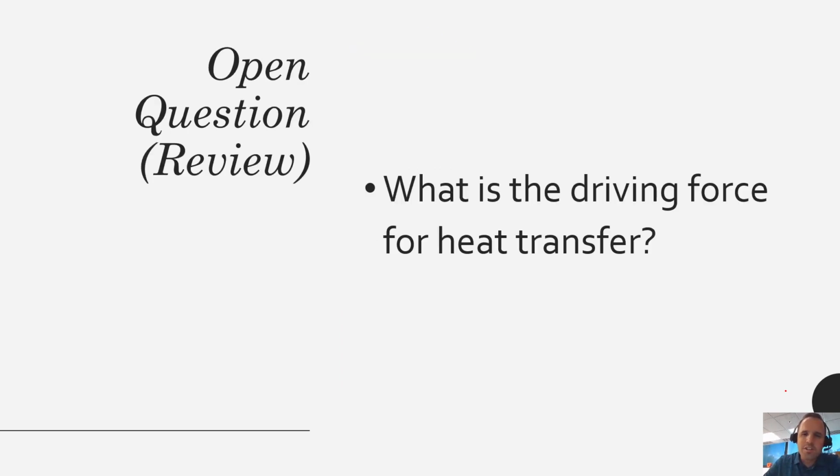So just a review question, this is the third time with this question because it's important. What is the driving force for heat transfer? And that is a temperature difference. For conduction, it was a temperature gradient because in conduction you're typically tracking how heat is moving through a solid. With convection, it's just a delta T, an algebraic T1 minus T infinity.